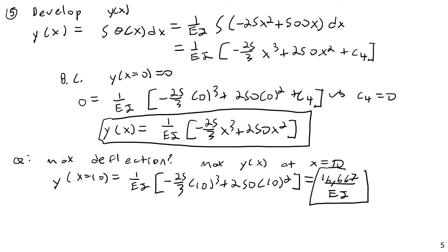All right, questions on that? Yes? What is slope and deflection measured in? Okay, so what is slope and deflection measured in? Slope would be measured in more like radians per inch, and deflection would be measured in simply inches, or whatever unit you have. So actually, I would like to give a few notes on this.